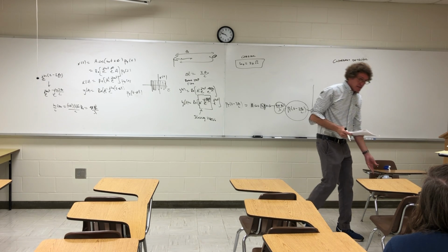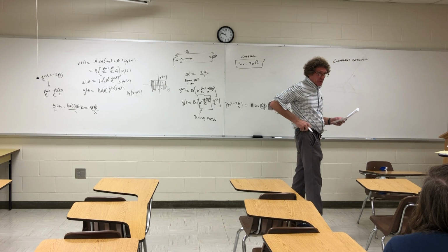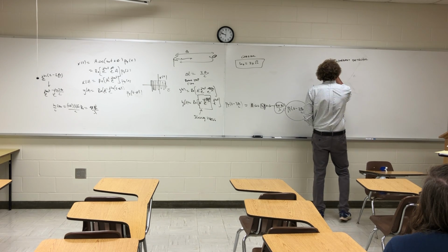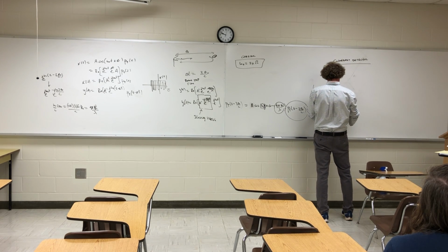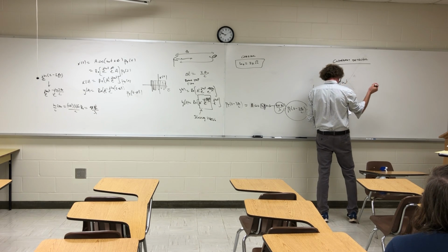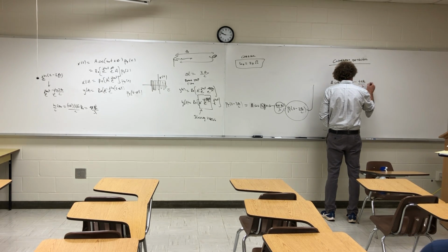And when we do this in the digital domain with sampling, there's a few things that happen that become very, very important about the timing. So this is a standard coherent detector, and it's in his book. He has an incoming signal A times cosine of omega naught t plus the phase angle minus 4 pi r naught, that's the range over lambda.